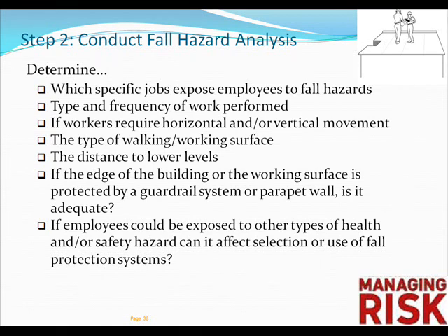Determine if employees will be exposed to any of the following: unprotected sides and edges, leading edges, floor holes, wall openings or hoisting areas, slippery surfaces, form work or reinforcing steel, ramps, runways or other walkways, portable ladders or stairways, excavations, working above dangerous equipment, obstructions, overhand bricklaying or related work surfaces, roof work, precast concrete erection, aerial lifts, or scaffolds.